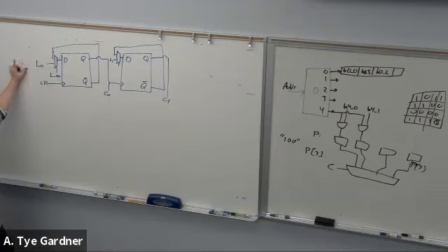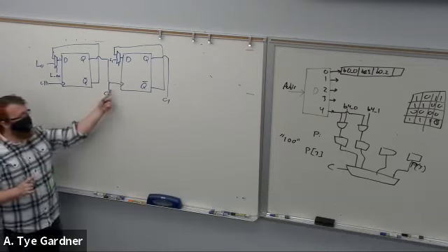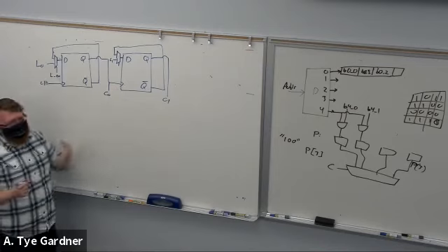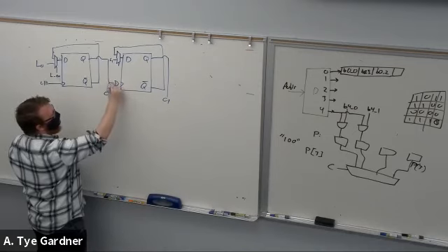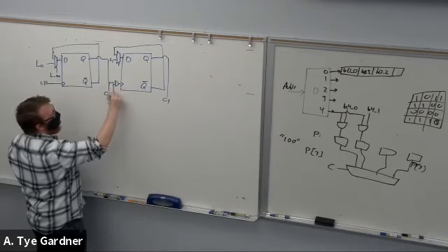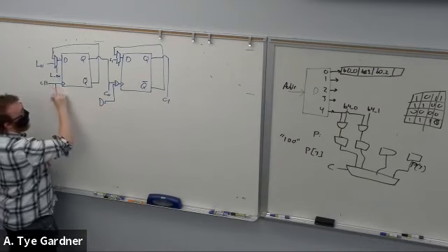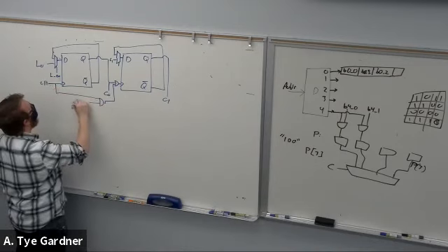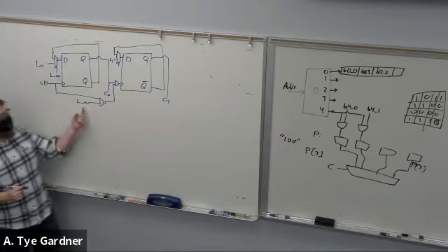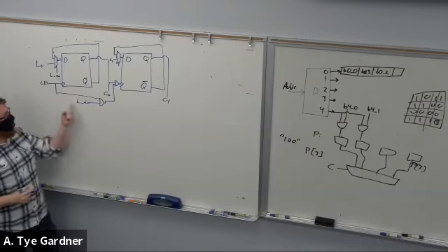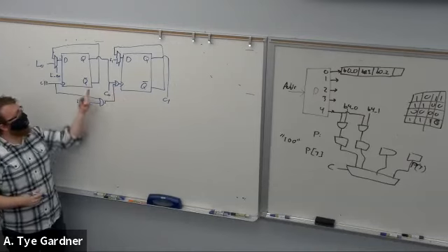So a solution off the top of my head, and it's possibly not the best one, but we already have a weird issue with this clock anyway, so I'm just going to go ahead and gate it. So if I have load enable, now I can pass this clock into here and update that.